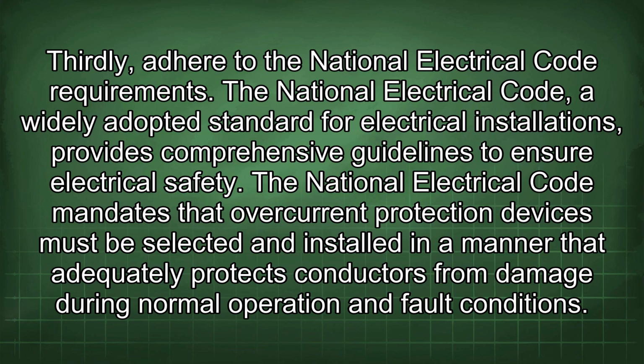Thirdly, adhere to the National Electrical Code requirements. The National Electrical Code, a widely adopted standard for electrical installations, provides comprehensive guidelines to ensure electrical safety. The National Electrical Code mandates that overcurrent protection devices must be selected and installed in a manner that adequately protects conductors from damage during normal operation and fault conditions.